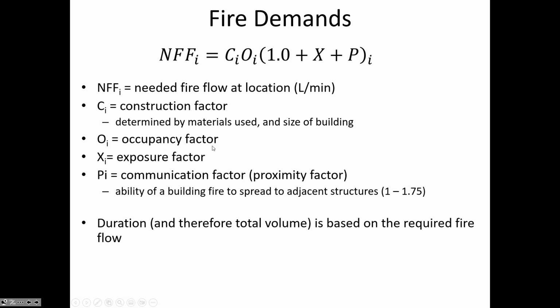The occupancy factor looks at, in some ways, the way that the building is being used and the potential risk for human life if there's going to be, for example, a hotel where the number of people in such a small space is relatively high. It may be important to have a sprinkler system in each one of the rooms, where compared to a larger room, you could have a sprinkler system that covers a larger area and maybe you wouldn't need as many of the sprinklers.